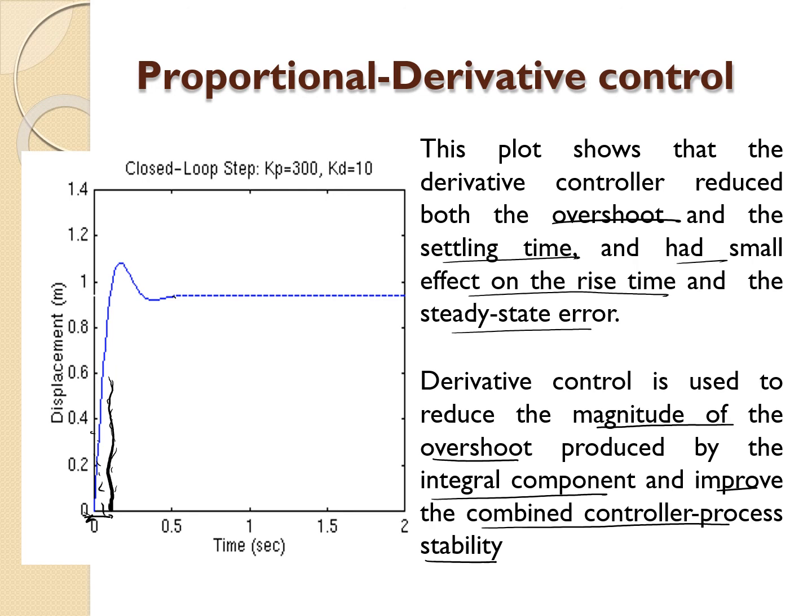So when we install the derivative control, this derivative control manages to reduce the overshoots. Please do not compare with the PI. You need to compare this proportional derivative control with the proportional control in the first response that I showed you just now, the first closed loop response.